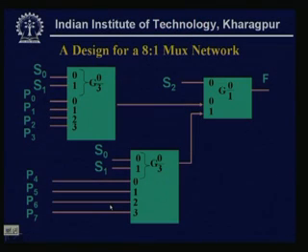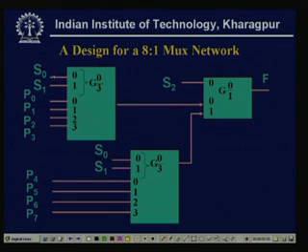Now this is just now what we have drawn, that if from that IEEE convention, if we maintain that, this is the conventional mux module, that 4 to 1 mux module, where S0, S1 are 2 select lines, P0, P1, P2, P3 are 4 input lines for the first mux.